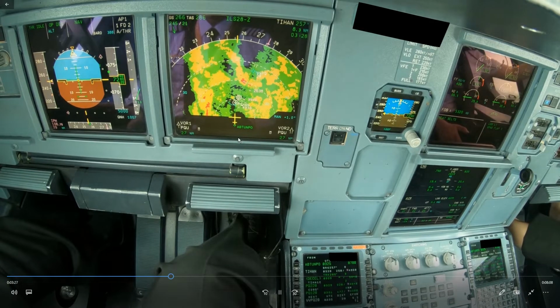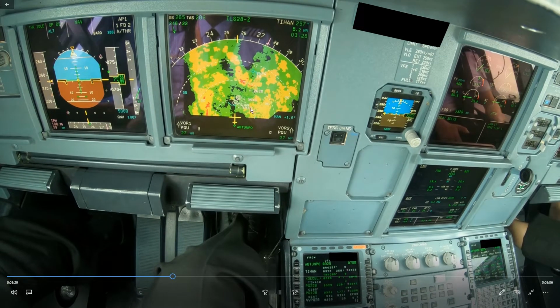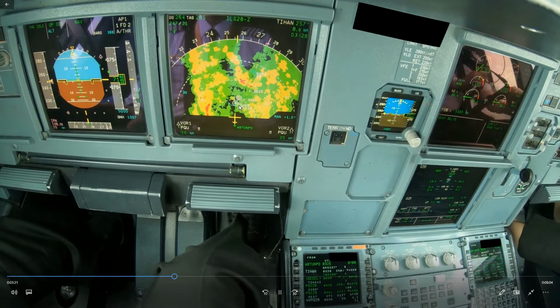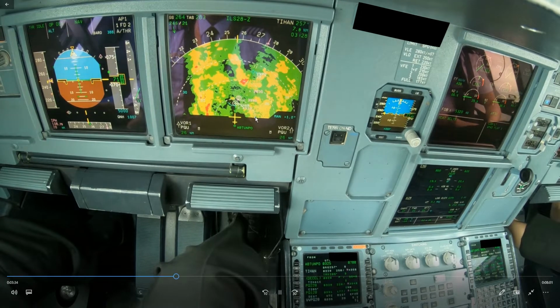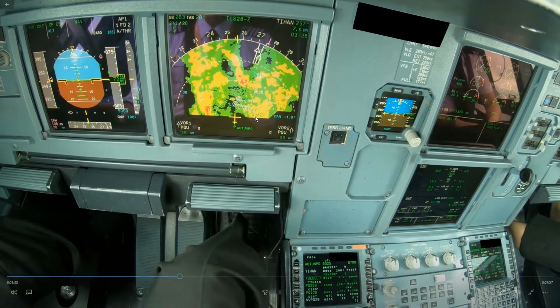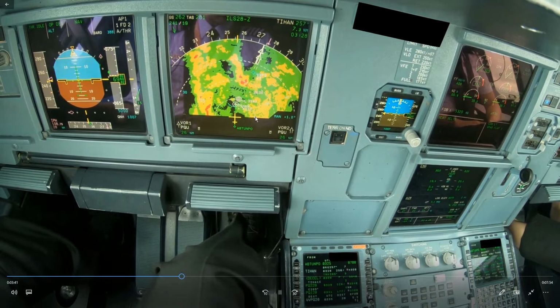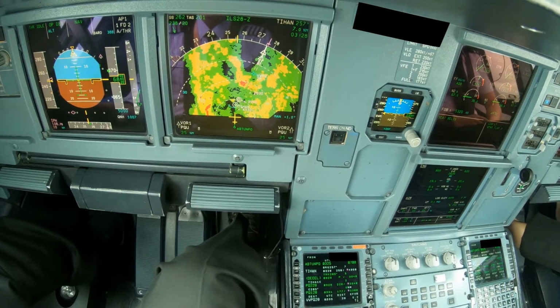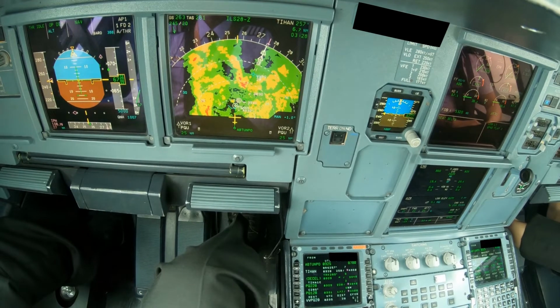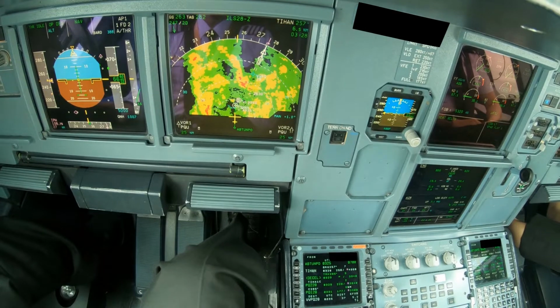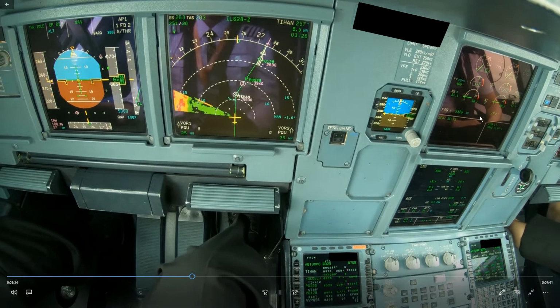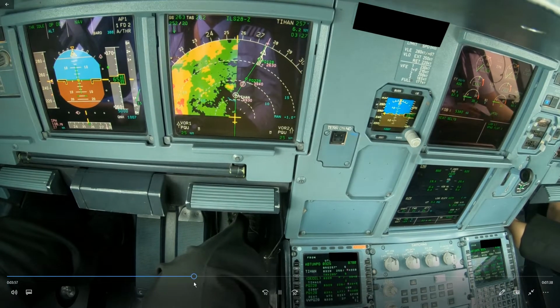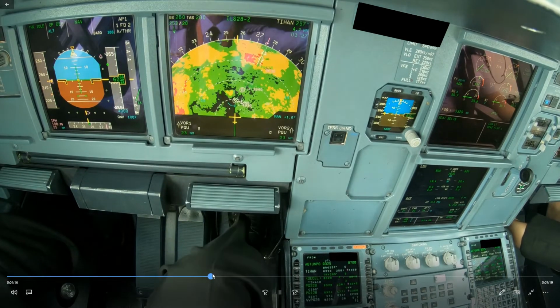But before that, you can see that 5,000 feet is actually the cleared level here at Tihan, and we cannot descend further unless we pass this waypoint Tihan. So because we are on profile now, or actually slightly above profile, once we fly level at that point, we have to slow down. Because if you need to descend but you can't, you need to slow down to force the thrust at idle. Okay, so let's skip ahead a little bit until we approach that point.